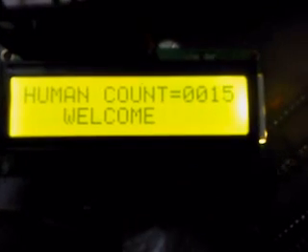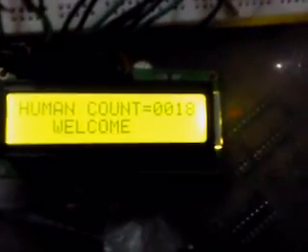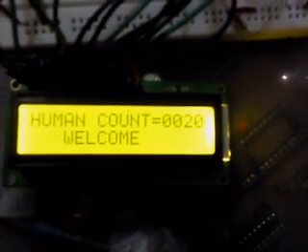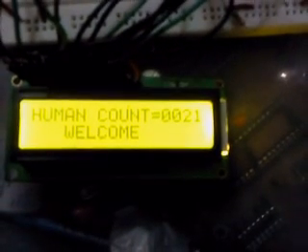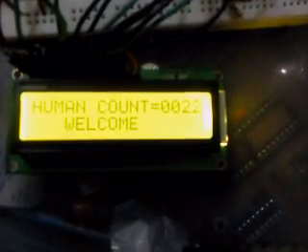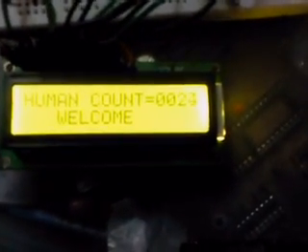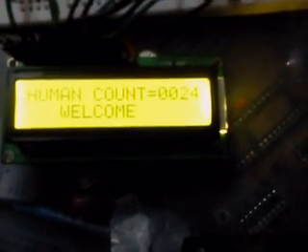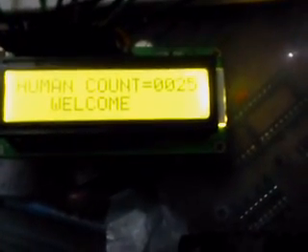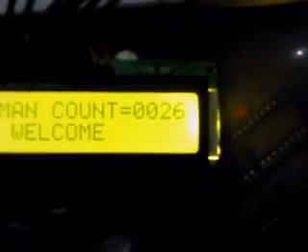But when the first person comes and makes contact with the IR sensor and the photodiode, it stops the IR rays for a few instants. LM324 is a comparator IC, and it compares the voltage of the first voltage and second voltage on its second and third pin, and makes the logic 0 in that instant.